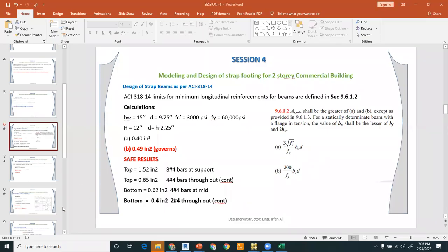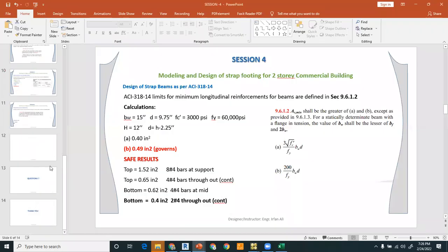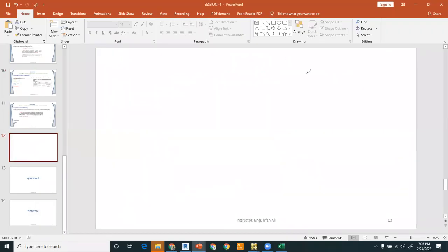नॉर्मली जो गवर्नमेंट्स के प्रोजेक्ट्स होते हैं, उसमें वो लोग वॉल फुटिंग प्रोवाइड नहीं करते। फॉर एग्जांपल आपके पास एक कमरा है, और यहाँ पे कॉलम है और यहाँ पे कॉलम है, तो आप इन सब के लिए आइसोलेटेड फुटिंग डिजाइन कर लेते, लेकिन आपके पास जो वॉल है उसको अपनी ज़मीन पे रेस्ट करना है, उसके लिए फुटिंग करनी है। तो उस फुटिंग से बचने के लिए वो कहते हैं कि यहाँ पे प्लेन बीम दे दें, तो हम वॉल प्लेन बीम से स्टार्ट कर लेंगे, और हमें वॉल फुटिंग देने की ज़रूरत नहीं पड़ेगी। ये एक रीज़न है।